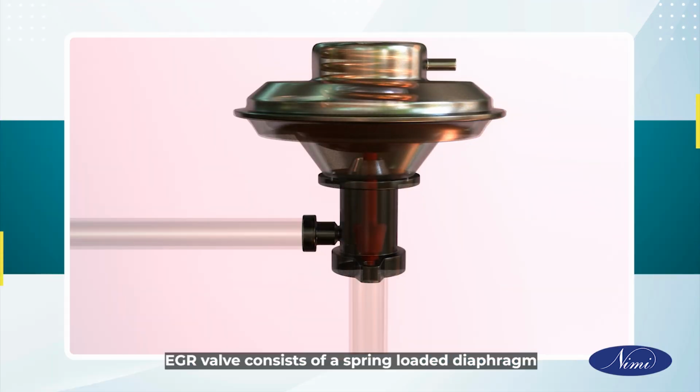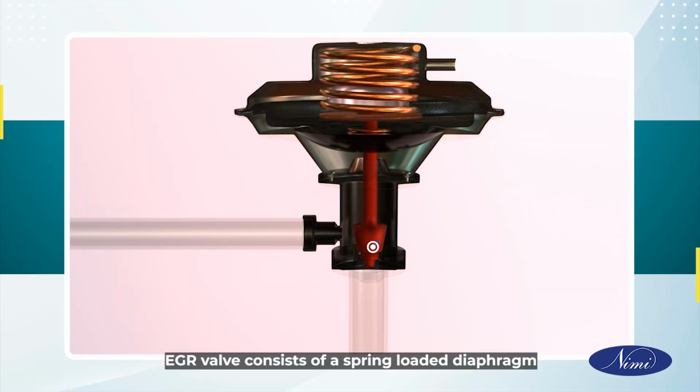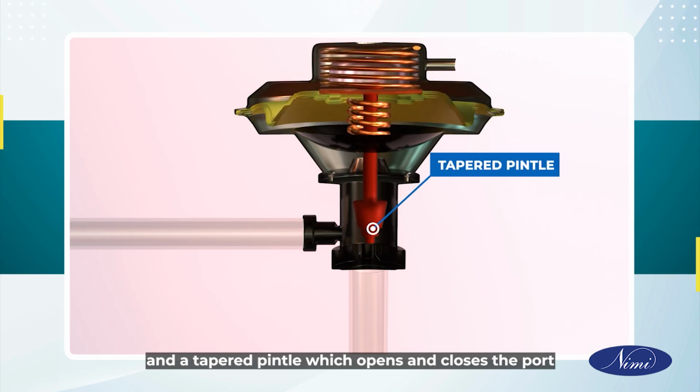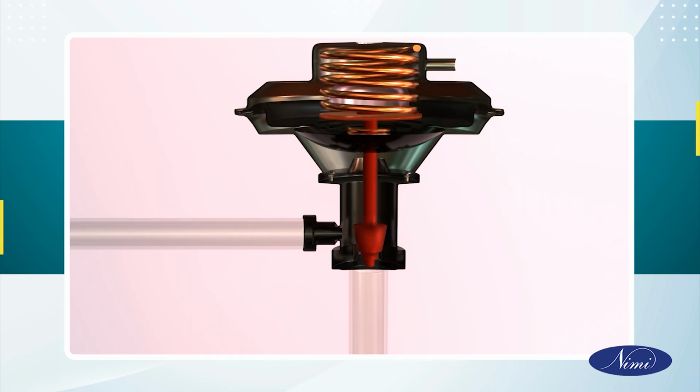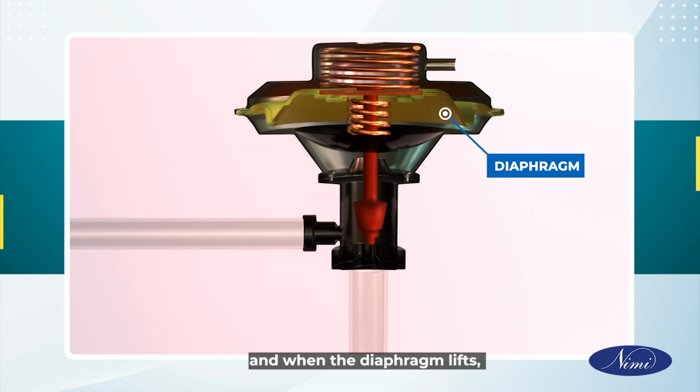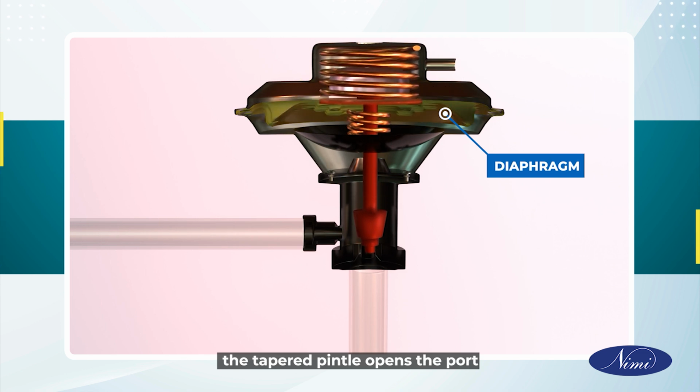EGR valve consists of a spring-loaded diaphragm and a tapered pintle which opens and closes the port. Normally, the pintle is in closed position, and when the diaphragm lifts, the tapered pintle opens the port.